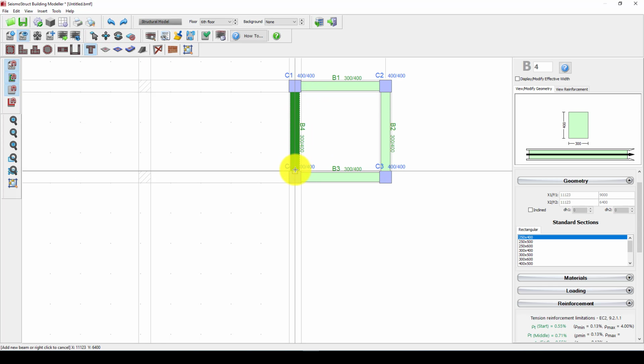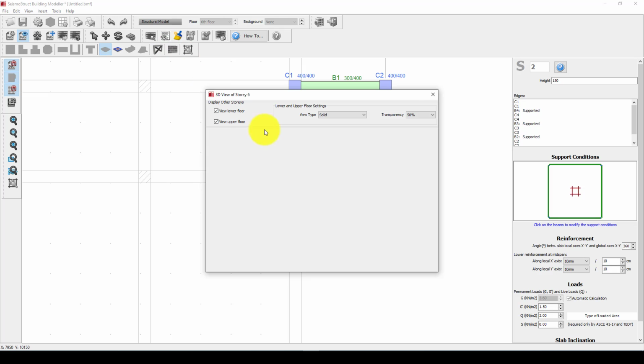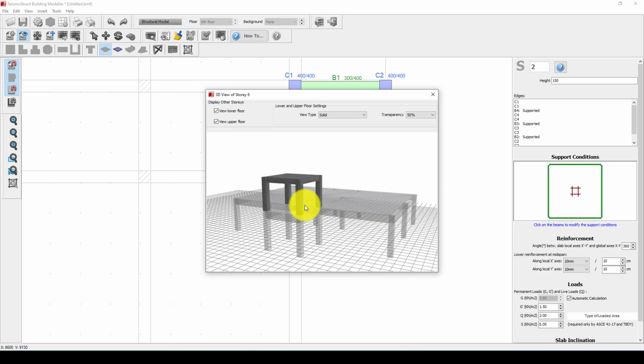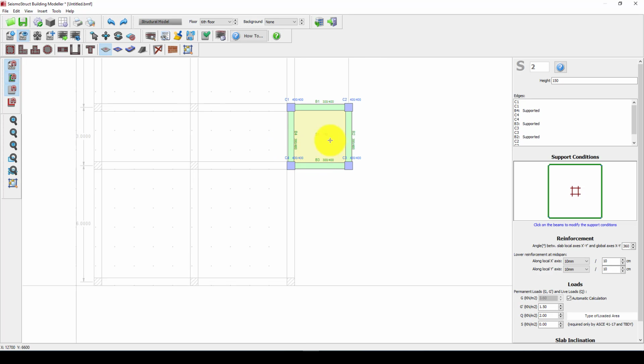Center to center. So the last one is we want to draw the slab in this floor. So we can go to the view, and the last floor is also completed. Now the modeling is completed. We don't have anything else because the program automatically gives some load. So suppose this load is already given as a superimposed load and also the live load.